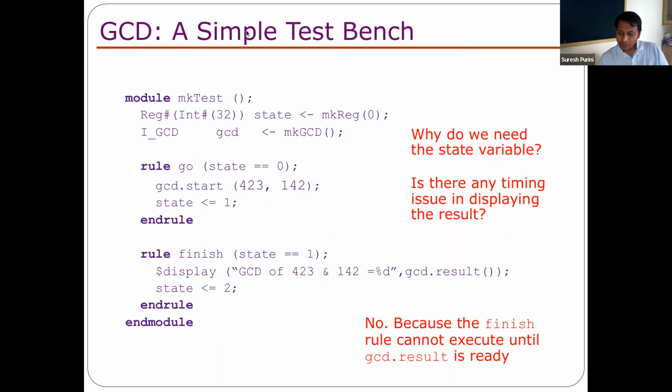The cool thing, as you can see, is that you can write your own test bench, you can have your module, and everything can be simulated. For example, let's say you have a design which parses UDP packets. Then in the test bench you can keep sending the UDP packets.